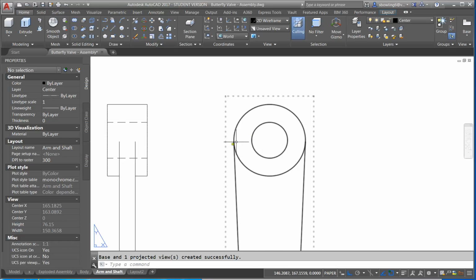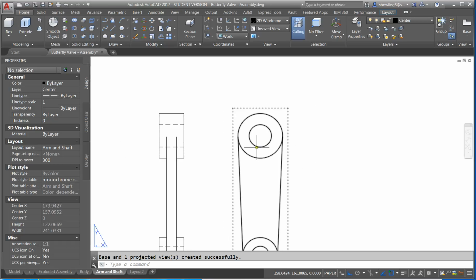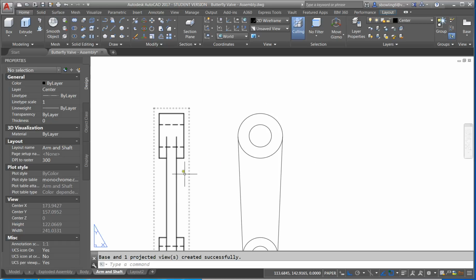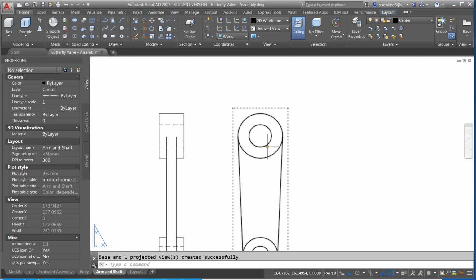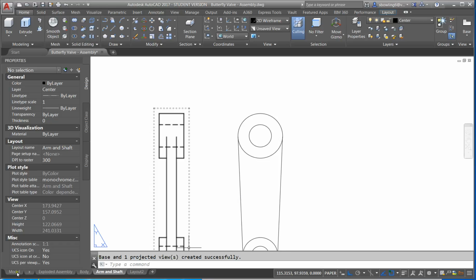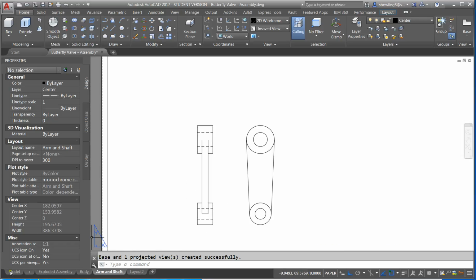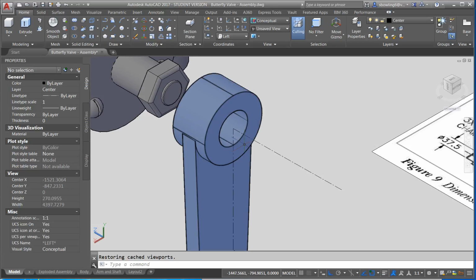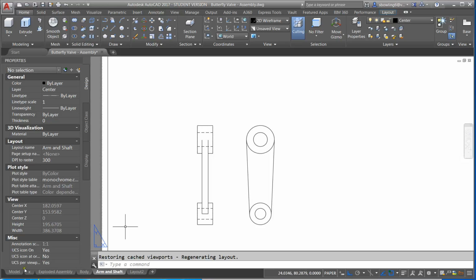Now the thing that I notice here is I'm missing the key cut. Well, I can actually draw that in now and fix it up as I'm going along. So the key cut is 7.7 in depth and 12.6 in width. So I'm going to go ahead and leave this, and I am going to, now here's something else you should know. Okay, so I can see these here.